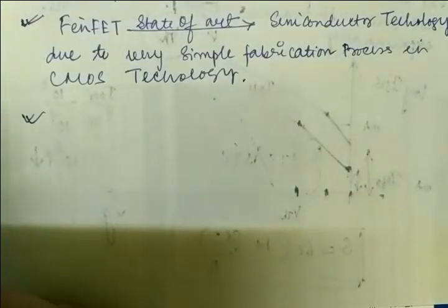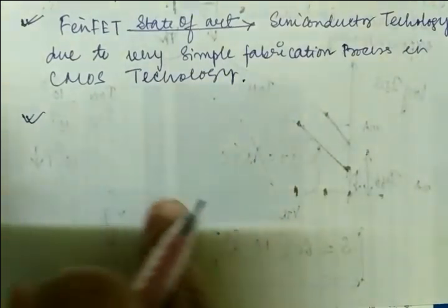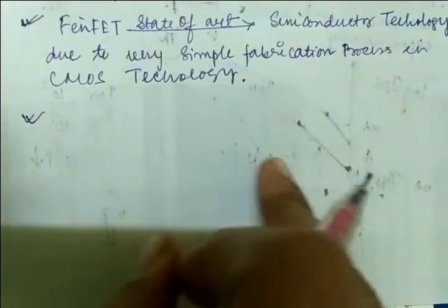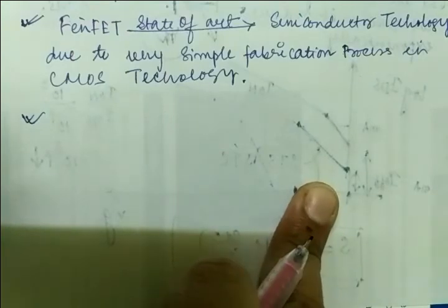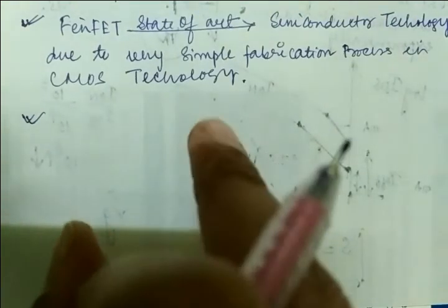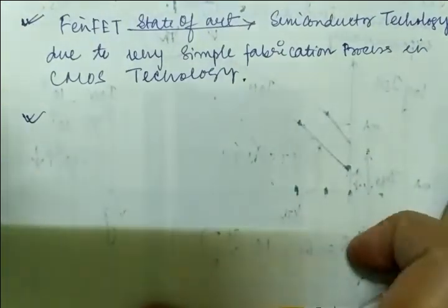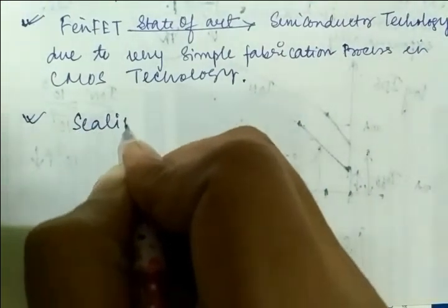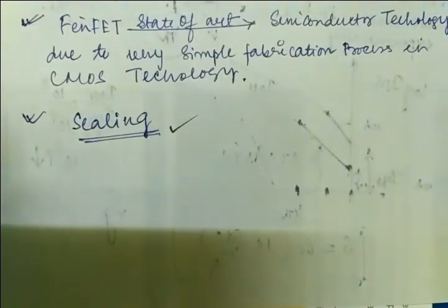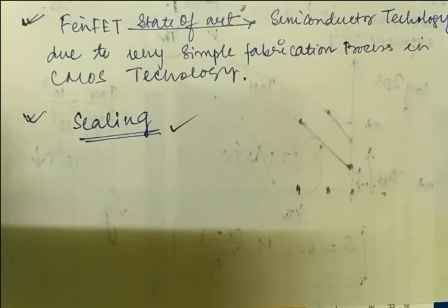And what is my fourth point? The power consumption in the transistor occurs mainly due to the switching action and leakage. That is also overcome here. And technology scaling results in a tremendous increase in the leakage power component. So scaling is very friendly. All other parameters associated with FinFET are a very good sign to use FinFET over the conventional MOSFET.